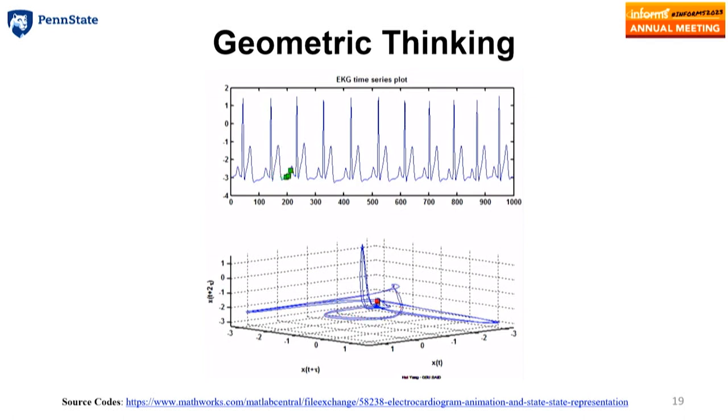So in this state space trajectory, we can study the divergence of two trajectories, and then we can see the Poincare sectioning, and what the distribution is in a particular area or a particular cross section, and also how they diverge. Then we can derive the Lyapunov exponent. So that's how people do nonlinear dynamic analysis. This is fundamentally different from traditional time series analysis. In nonlinear dynamics analysis, people look at the trajectory in the high-dimensional state space.